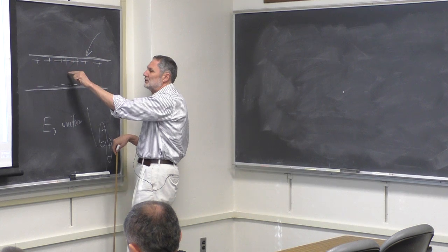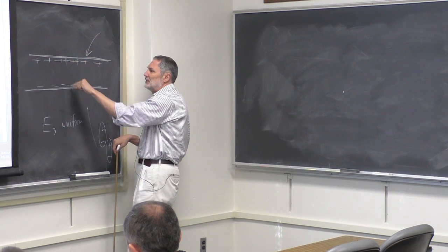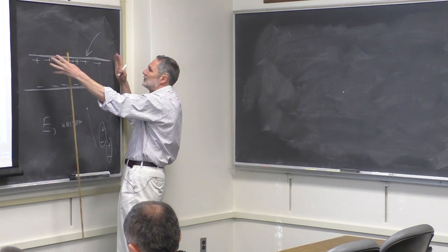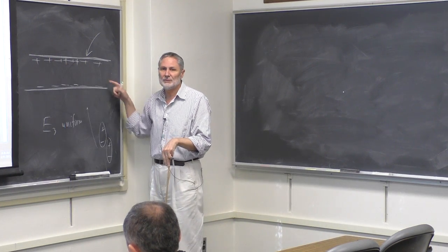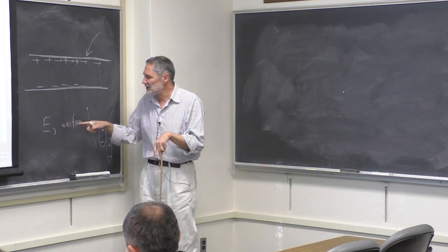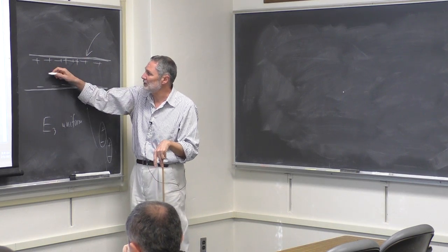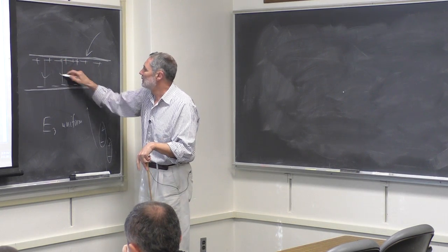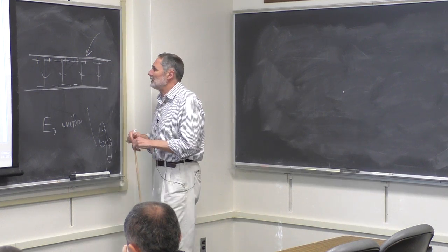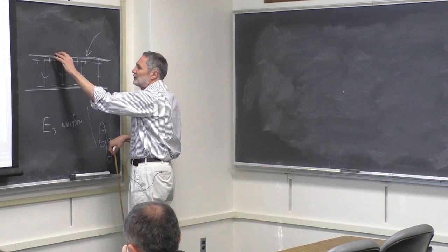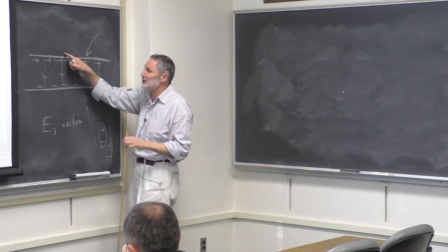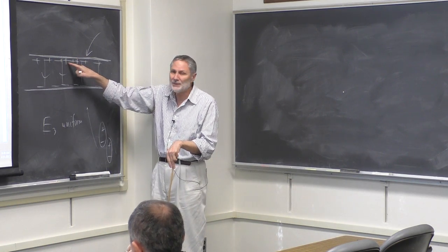So this is going to tend to increase the electric field, but the free charge is going to reduce this to keep the electric field uniform along here. So whereas the electric field has to be uniform here, the displacement field, which is dictated by the free charge, is going to be non-uniform because the free charge has to be non-uniform. It has to compensate for this.